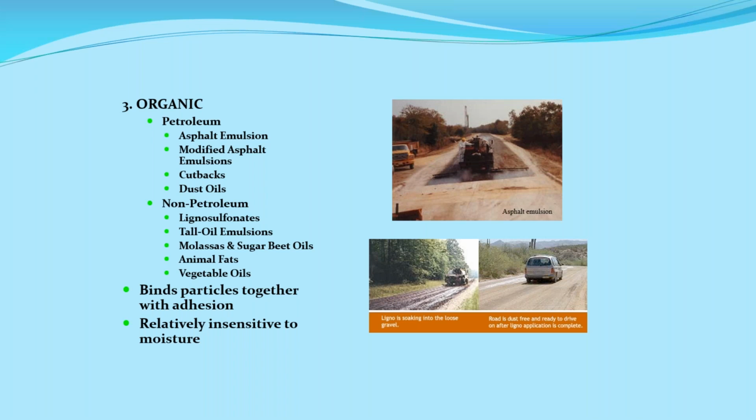your material. And so what some of the companies are doing is they're taking lignin sulfate or your tall oil and mixing it with magnesium chloride, because then the magnesium chloride helps to take and transport it down into the material a little bit better, and also gives them the reworking ability, because the lignin sulfate, the tall oils, all those types of products, when they dry in your road surface, they get hard.